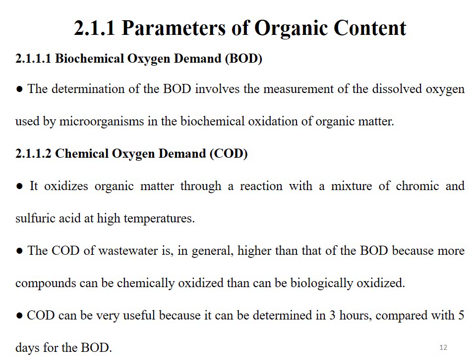The COD of water is in general higher than the BOD because more compounds can be chemically oxidized than can be biologically oxidized. And COD can be very useful because it can be determined in 3 hours as compared to BOD, which takes 5 days for its determination.